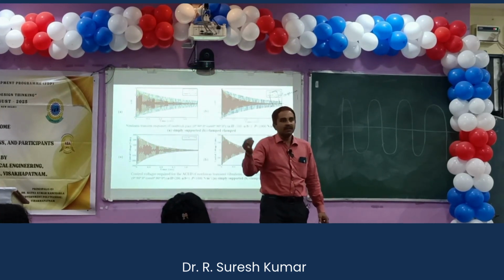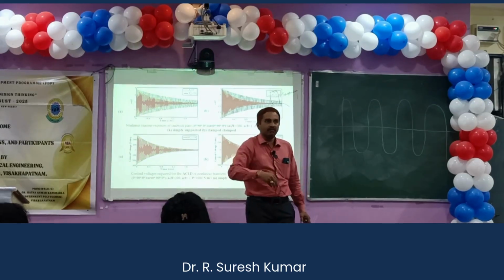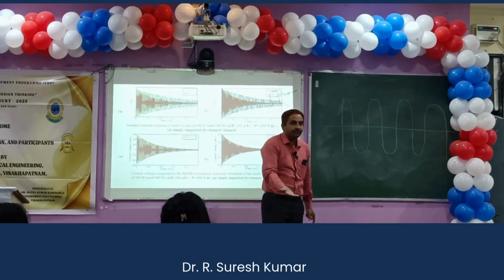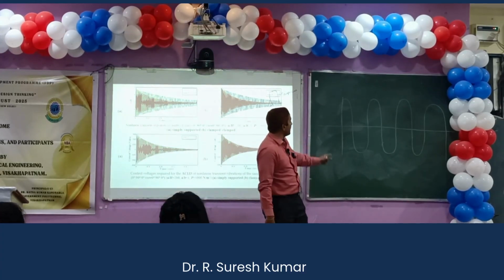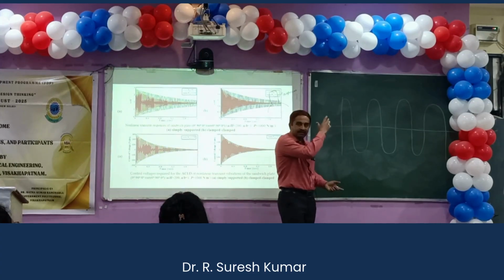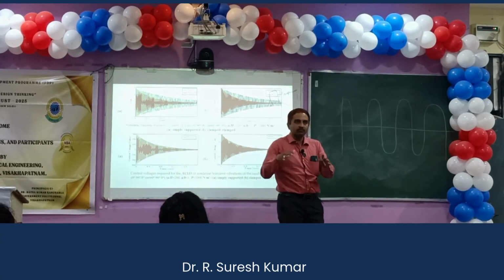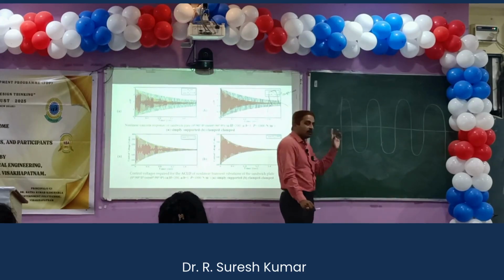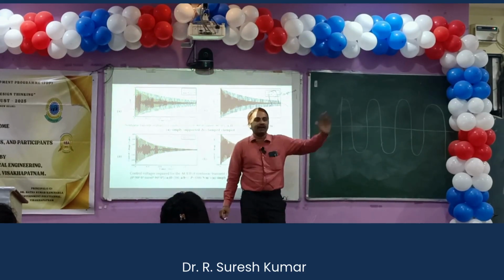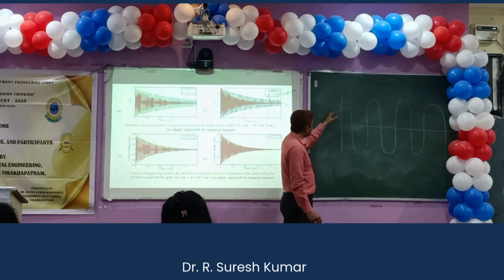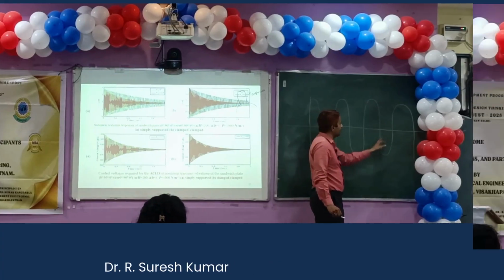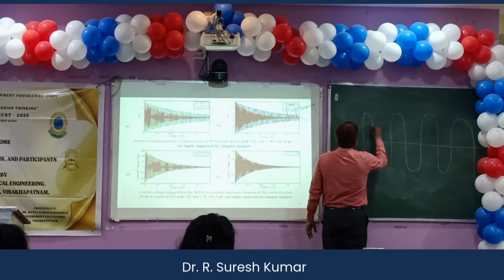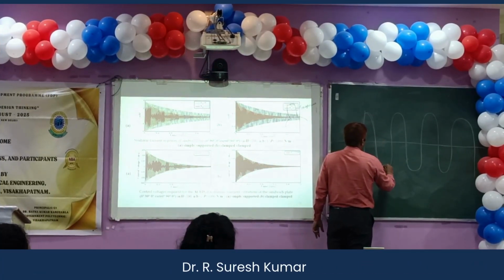Why is it reducing? Because there are wind loads and external factors, and there is friction, and this material has got certain damping. So after some time, the damping is causing the vibrations to reduce over a period of time. But according to Newton's first law, it should not reduce; it should continue to vibrate, right? So if you give free vibration, the free vibration response will be like this. The damper will reduce the vibration.